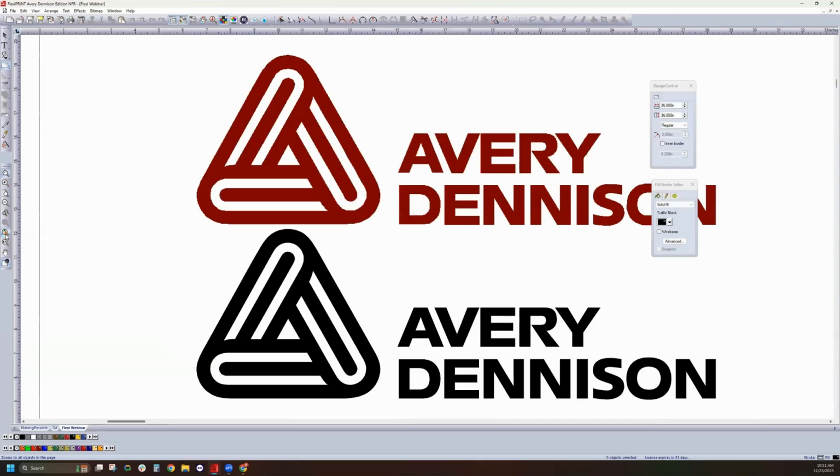If I click that, it takes everything on my artboard or my workspace and fits it inside the viewable area that I have open. This is really helpful if you have a random artifact somewhere off in the distance of a file and you're not sure why the file is bigger than it should be, you can press zoom to all objects and see if it zooms way out to find a little floating object somewhere.